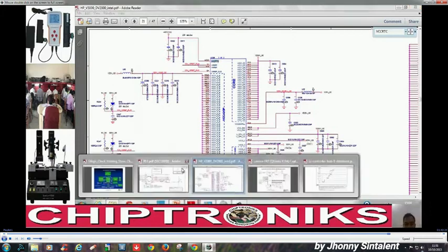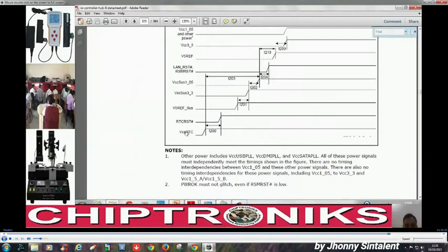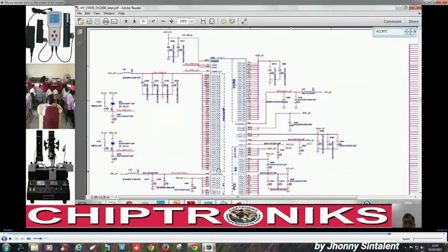You can see in the data sheet VCC RTC is the first voltage, right? So we go in the schematic diagram, we have searched exactly VCC RTC and it is connected to +RTC_VCC. Now we'll see from where this RTC VCC is coming.